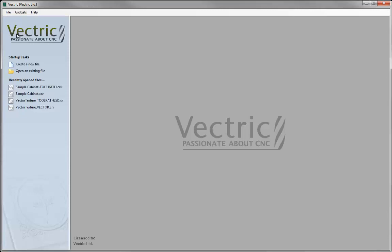What I'm going to do now is demonstrate how we go about creating a new file with all the exported vectors that we have created from our cabinet maker's design package. Some cabinet maker's design packages may export these vectors as DXF files, and they might export a DXF file purely for every single vector that's been created. So we may end up with quite a lot of DXF files that we need to import into this software. So it may not be done on a per layer basis.